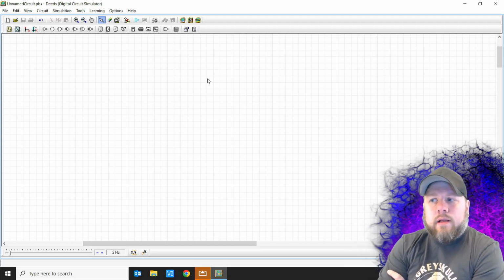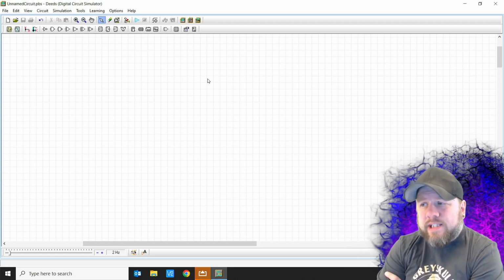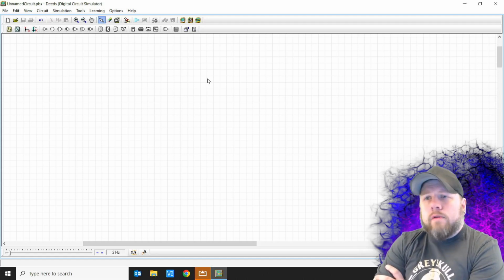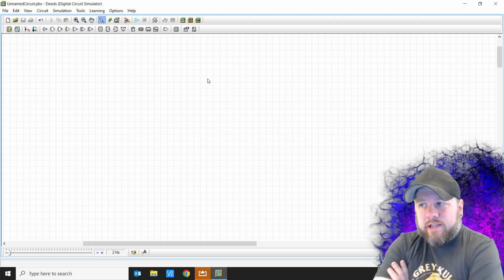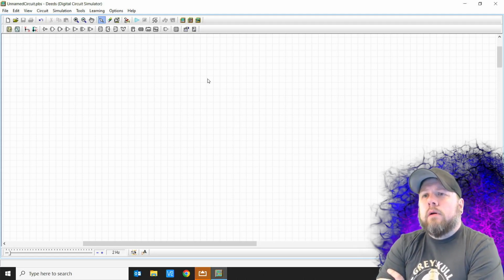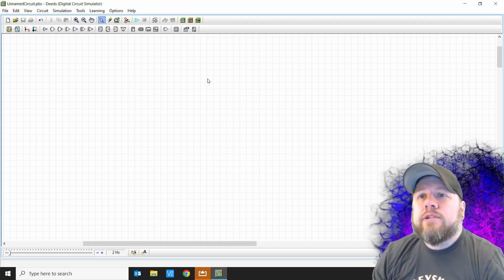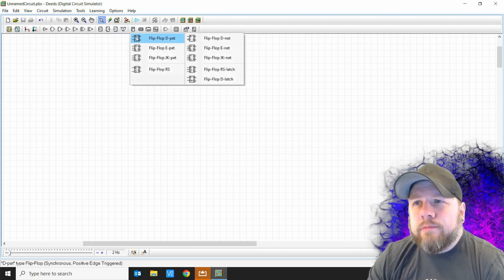So let's say that flip-flop. Instead of building it from scratch, ANDs, ORs, and NOTs, over and over again, we could draw a box and say all of that circuitry is in there anytime I say the box. And we're able to abstract it and make clearer schematics. So since we've done a flip-flop from scratch, we can start using flip-flops.